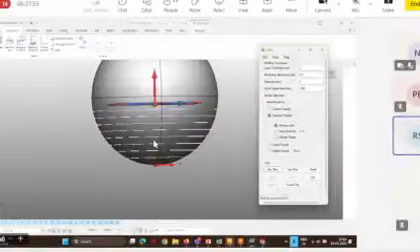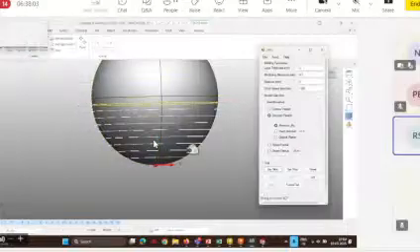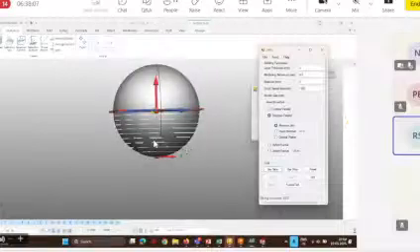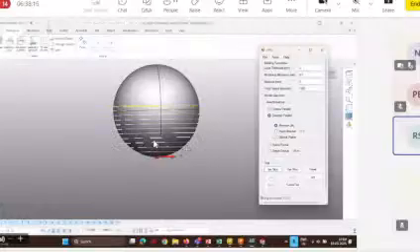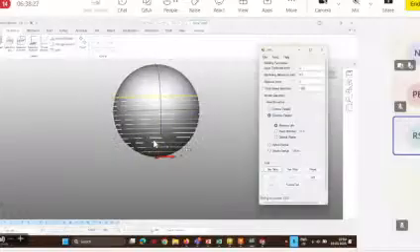And it's showing how many total layers will be required, like 21 layers. To automate how many layers will be required, you can do one more thing, like you did while recording the macro: you can select the model and select the bounding box. From the bounding box you know the maximum height, and you also know the layer thickness. So from there you can actually calculate how many layers will be required.